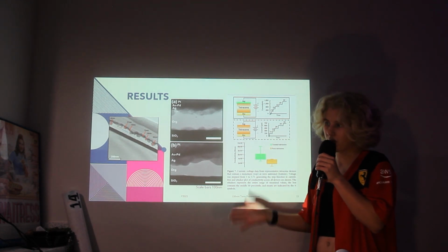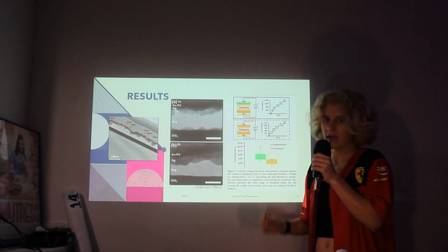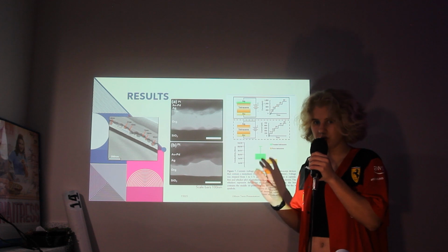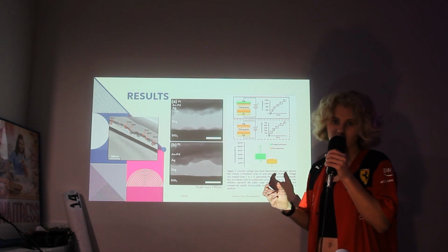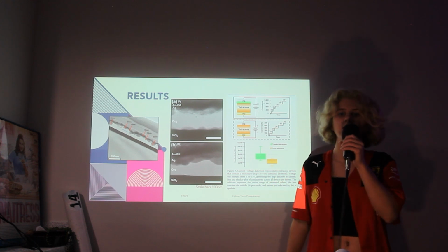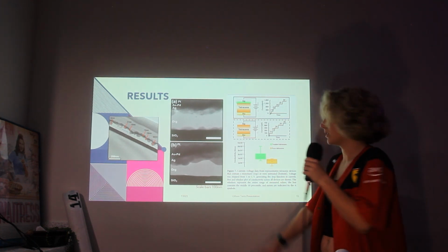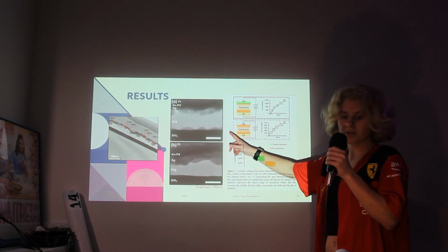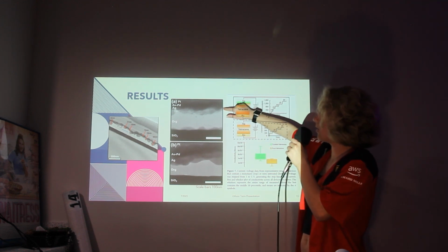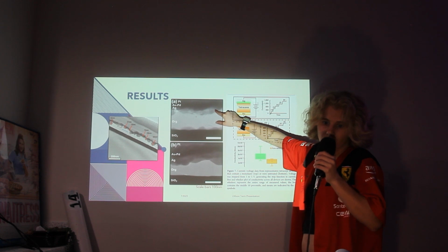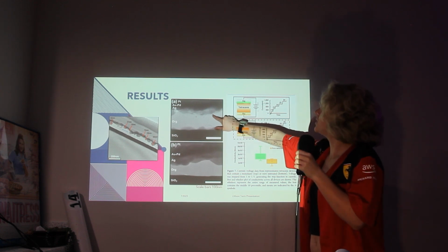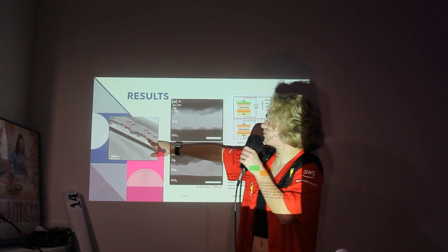They tested both parallel and perpendicular tetracene and had the same issues with grain size. The results are also in line with reported problems with thin electrodes, especially those in top emission OLEDs. So in the middle, you can see decreased grain size at the interface of the metal and organic layers, and how much smoother it is.